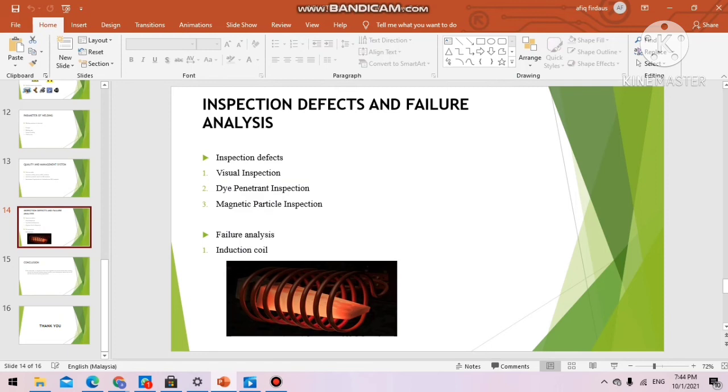Induction coil failure is a rather difficult problem since there is normally no sole trigger responsible for the failure, but rather a variety of causes that are interrelated. A coil failure analysis must at least draw on experience of electromagnetics, metallurgy, material science, mechanics, heat transfer, and chemistry.